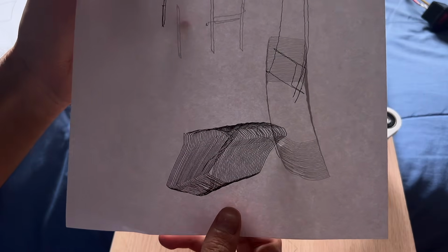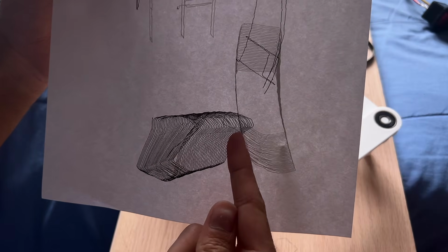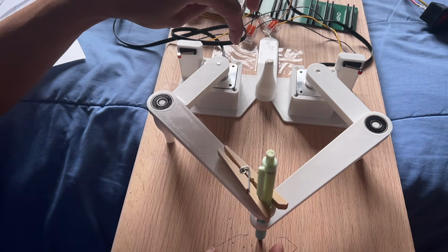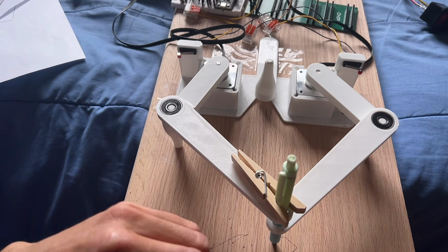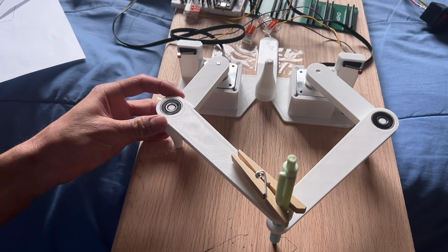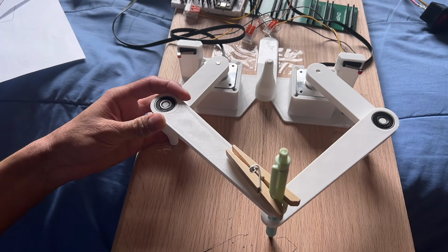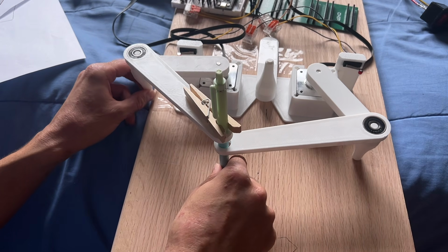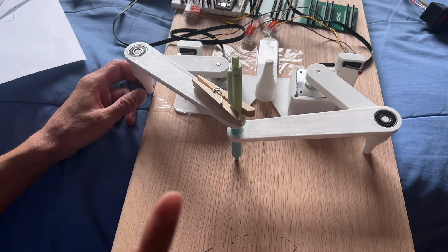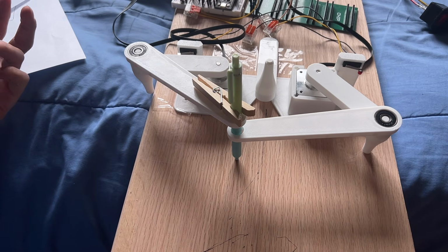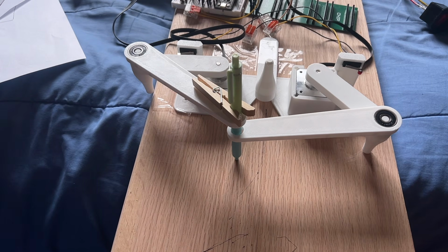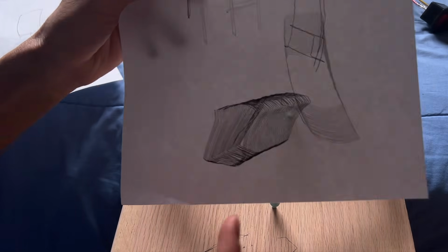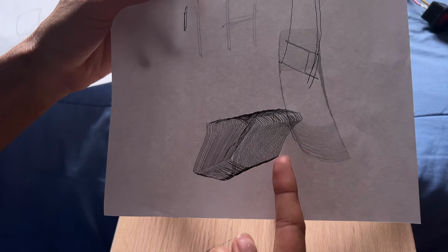You can also see in this picture here that it is moving to the side a little bit. Now, I believe it's doing that because the way I have it set up right now is it's reading the step angle and then calculating how many steps it's going to take to get to the angle, or to get close to the angle it should be at. Now, it never actually gets right to the angle. It's slightly off. It could be off 1 degree, a fraction of a degree. It changes every single time it does the calculation. And I believe that slight offness is causing it to do this right here, where it just slowly moves.